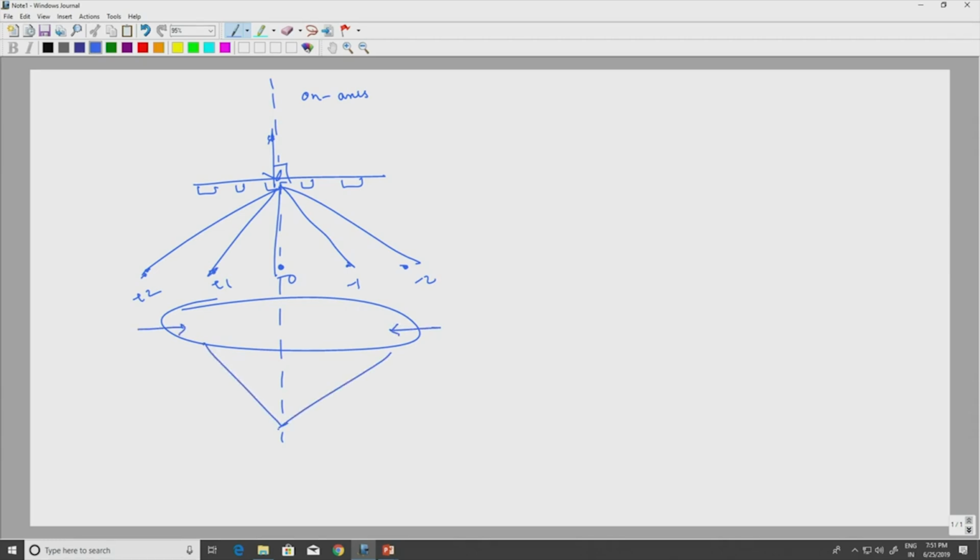So now if I get a situation where your dimensions are reducing, that means I have a very small pitch. We know that when you are illuminating this sort of small pitch, you will have your zeroth order, but your first order itself is going to be outside.